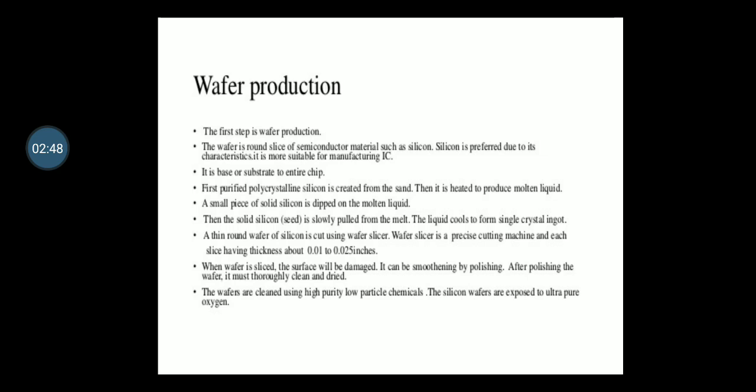0.025 inches. When the wafer is sliced, the surface will be damaged. It can be smoothed by polishing. After polishing the wafer, it must be thoroughly cleaned and dried. The wafers are cleansed using high purity, low particle chemicals. The silicon wafers are exposed to ultra pure oxygen.